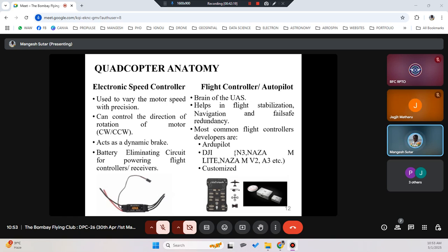There are drones, like yesterday I showed you on the digital sky platform, the second drone made by Crystal Ball, that drone has a mechanism called a parachute. Lot of people have purchased it and tested it, but it was not really 100% successful, because a lot of the time the parachute gets stuck between the propellers and the propeller pulls the parachute down. It gets entangled between all the things, so it is not a 100% successful recovery mechanism.